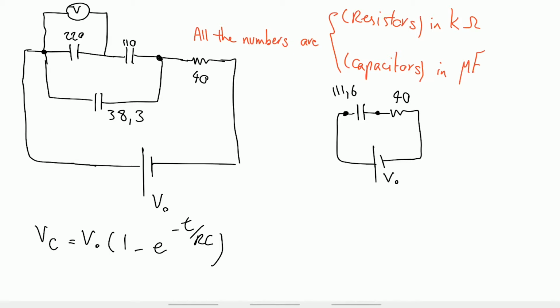One more thing we have to mention is that when 2 capacitors are in series form, and, for example, here is connected to the ground and here is V volts. If we want to calculate how much of the total voltage is on this capacitor and how much of the total voltage is on the second capacitor, we have to know that in capacitors which are in series form, the total charge on C1 equals the total charge on C2, right? Because if there's a difference, then there will be a current flow. As there is no current flow, it means that the charges are the same.